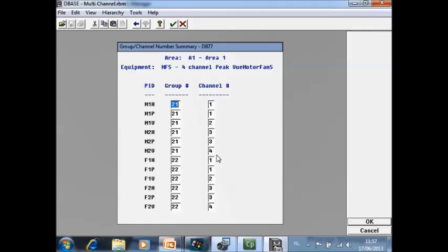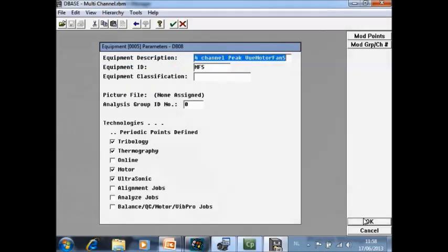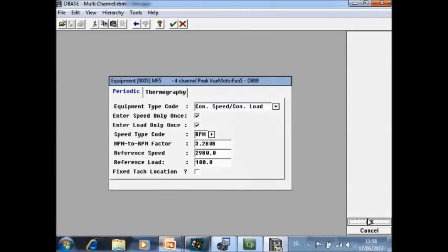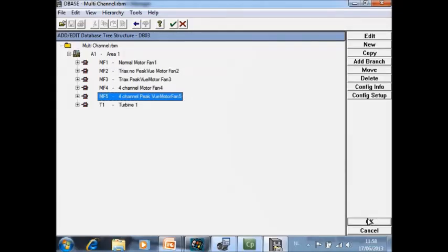So you're limited to 4 channels simultaneously. However, if you configure more, he will measure more with only starting the acquisition once. So more or less it creates an illusion that he's even taking 6 measurements simultaneously. All those settings were for roll element bearings.